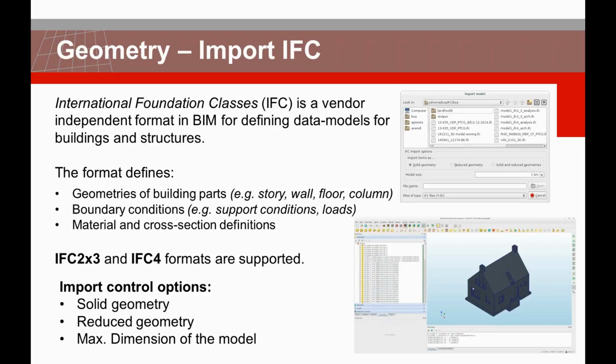And if you have a model, for instance, in Revit or any other modeler that is possible to generate IFC format, you can basically transfer your geometry components or bodies based on the solid, based on the shell or the sheet faces, based on the beams, their associated cross sections, and the material properties that you are assigning to those geometry components. You can transfer all of them as a complete geometry into DIANA.